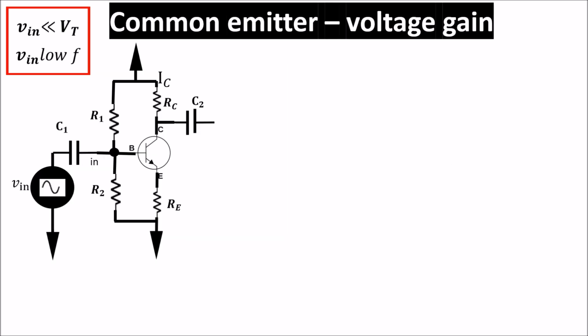In order to improve the voltage gain, we use a bypass capacitor. In this way, we don't affect the biasing point in which we need emitter resistor, because the capacitor in DC is like an open circuit, but in AC, if it is set properly, it behaves like a short circuit. So remembering the impedance of the capacitor is this, I want it much less than Re.